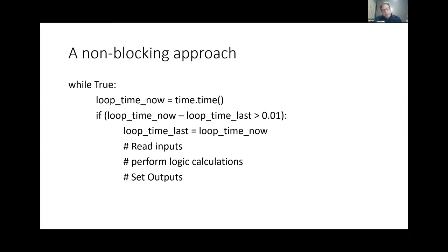Now, it's not so evident here when I'm showing reading individual GPIOs, but when my IO cards, where I've got 8 inputs and 8 outputs, and I'm actually coming in through the I2C bus, a single read instruction actually reads in 8 inputs in one instruction.